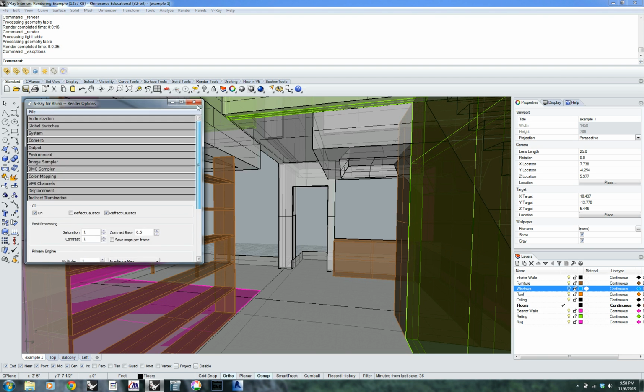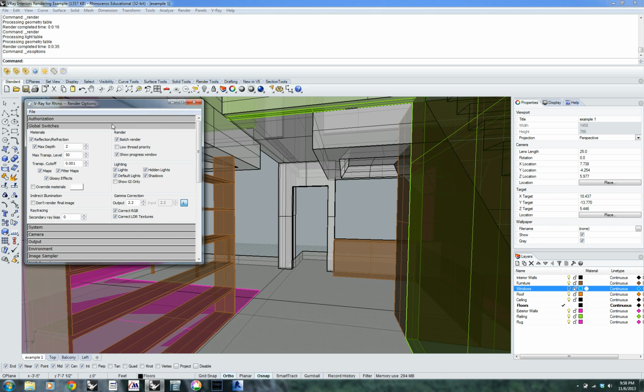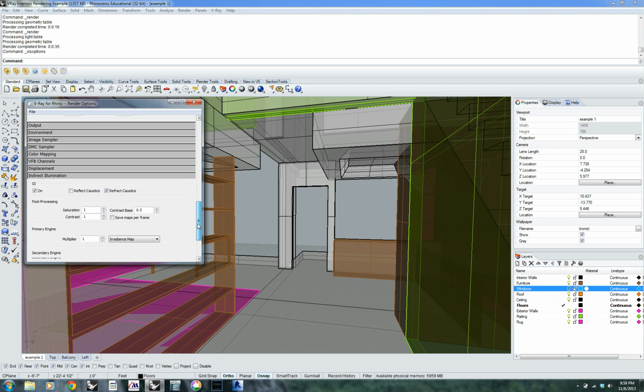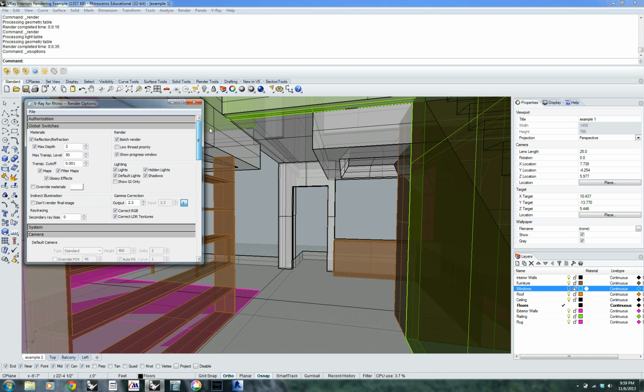Okay, there's a couple other settings that I'm going to change off of the basic settings. If you come into camera, you're going to notice that this box is probably checked, vignetting. So I'm going to go ahead and turn that off. That's kind of dark corners around the edges, and you can do that in Photoshop, but you want to have a more raw image to start with.